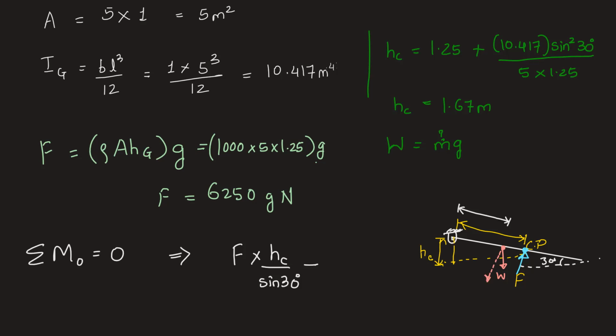So we can take distance of CG also along the direction of the gate. This might denote that distance. Component of weight in this direction in the dotted one, this angle being 30 degree, will be W cos 30 into this distance, which is simply 5 by 2, that is 2.5 meter. We already saw this. This will be equal to 0.